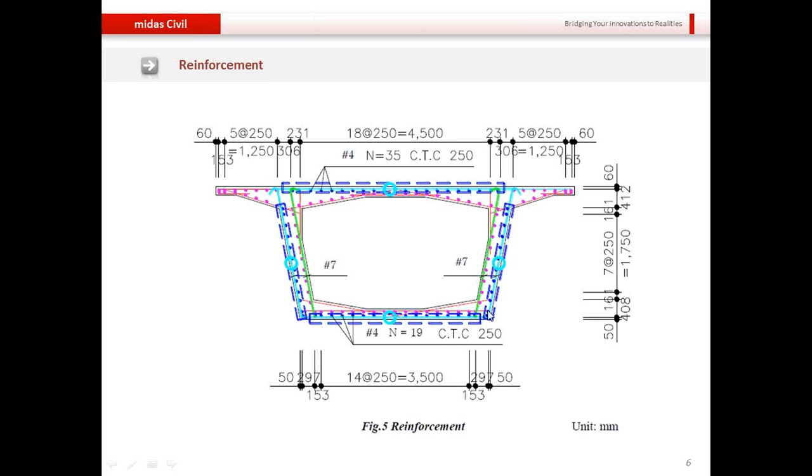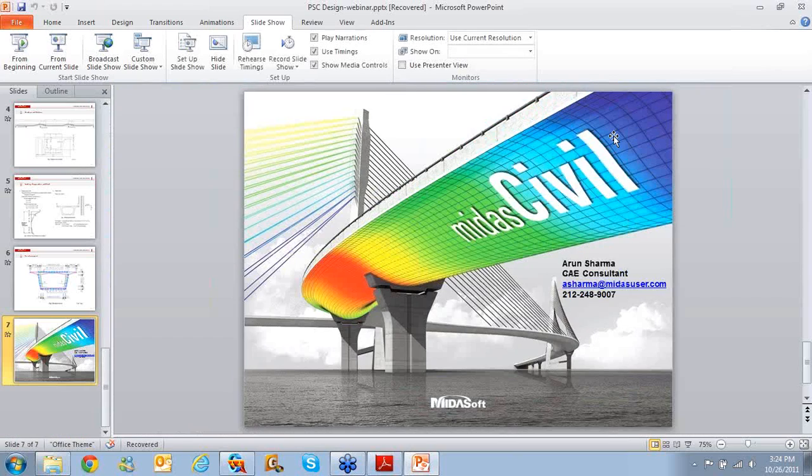So basically these are the closed one-legged stirrups, the blue color ones, and surrounding them or distributed around them are the longitudinal torsion reinforcement. I hope this explanation is clear.